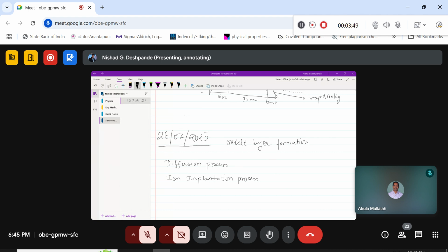Okay, so we talked about this very important part: why radical oxidation is important, because we already have wet oxidation and dry oxidation, but then why do we require another, radical oxidation. We talked about that along the contours, whenever you have such kind of sharp edges or a contour, in that particular case, if you try wet or dry oxidation, then you don't get a proper contour of your silicon dioxide throughout the edges of this particular silicon.